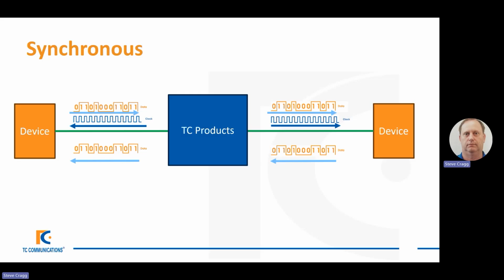The important thing to remember in all of this is that each device will either send or receive the clock, and it will use that to either send or receive the data to make sure that the data is synchronized to the clock. And that's the most important part. So that really covers synchronous communications.